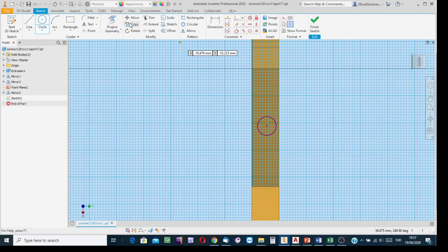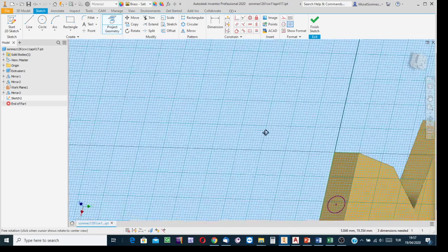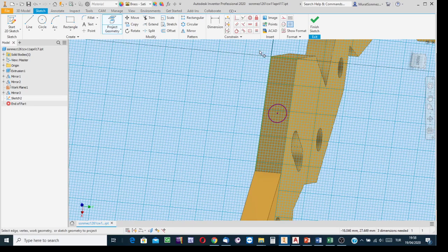Okay, and then use the project geometry process to locate this circle with respect to this edge. I created it as a projection with respect to that edge. Yes. And then, using these projected lines as reference, anchor this sketch. With respect to here, the distance is, say, 10 units. With respect to that edge, the center point is 40 units away. And the size of this circle, which in my mind corresponds to the base of a cylindrical extension, is 12.